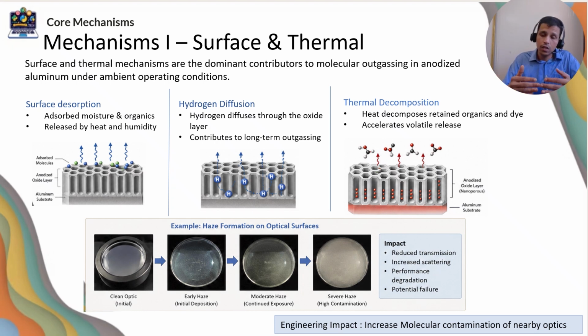In addition, while anodizing, to add a color, if black color is needed for an optics mount or anything, black dye or color pigments may be added based on the required color. Those organic dyes, due to this temperature, will start to decompose and release volatile elements. Those elements will affect and contaminate the optics.